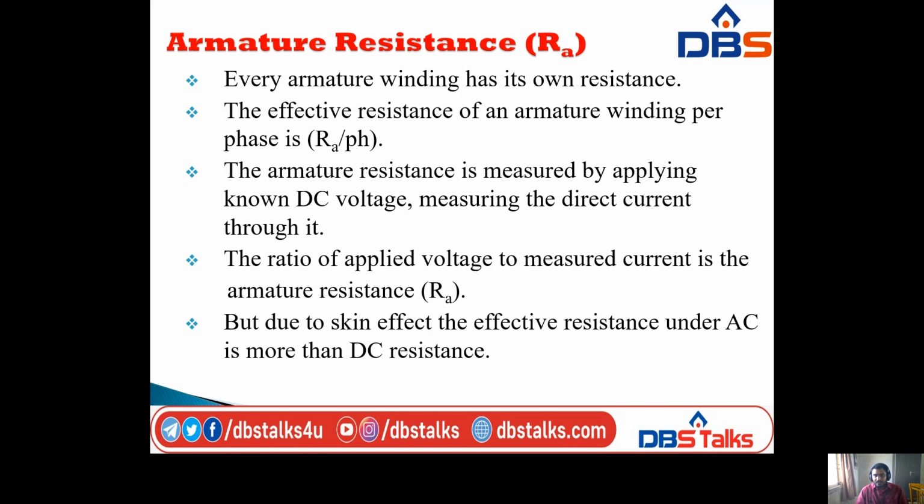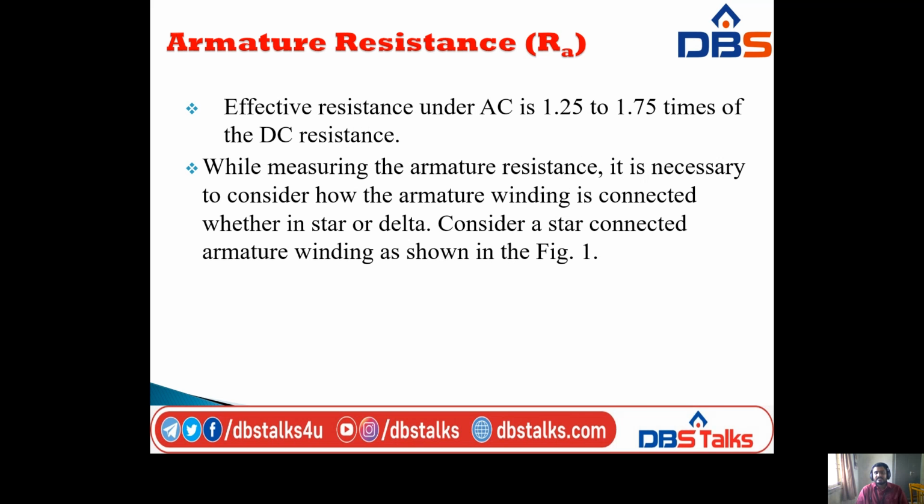Okay, but due to skin effect, the effective resistance under AC is more than the DC resistance. How much value we have, I will discuss here. So the effective resistance under AC is 1.25 to 1.75 times the DC resistance.